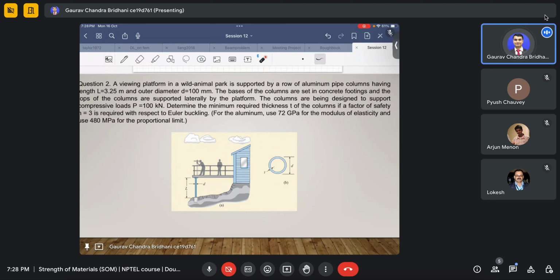Now if I ask you in which direction it will buckle, you know that for this case the I value, or the second moment of area or the moment of inertia, is the same for all the directions, be it Ixx, Iyy or Izz, whatever I call it. So here you can't say in which direction basically. Now it depends. As the professor also spoke about in one example in the lecture, there are figures which have the same I.